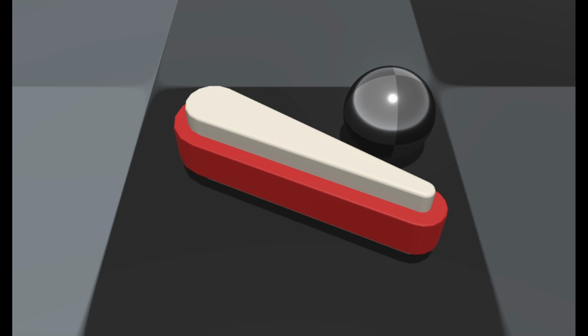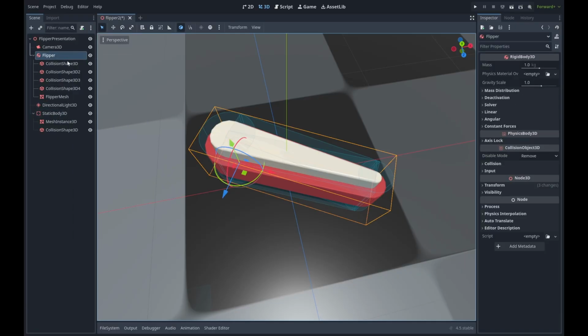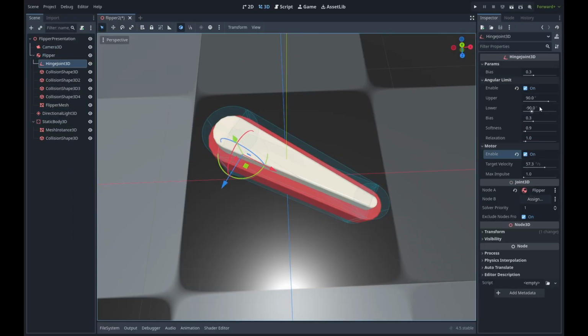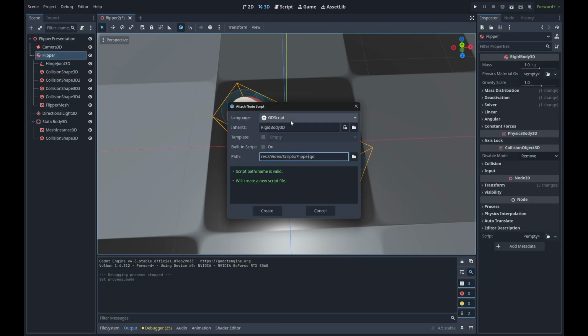Now that we have a visually recognizable flipper, it is time to add the physics collision shape. Two cylinders at the base and tip using the same radius values, and two boxes that make up the tapered edges that follow along the length of the tangent line between the two circles. I'm converting it to a rigid body object and attaching it to a player-controlled motorized hinge. The hinge will have rotation limits and will freeze or turn to static when it reaches those limits.